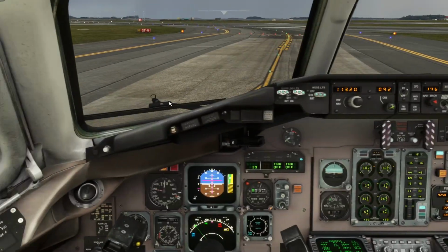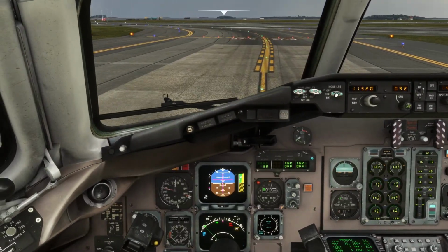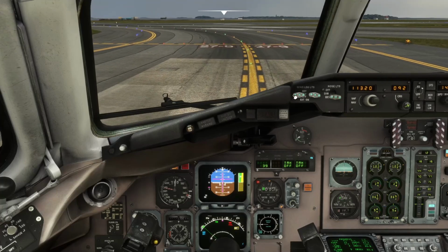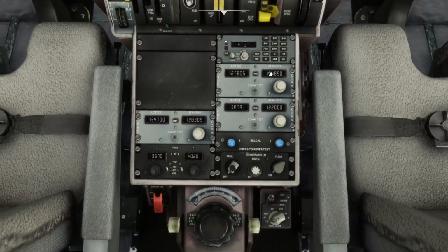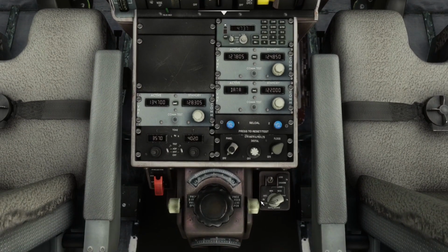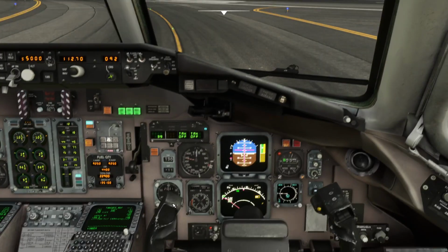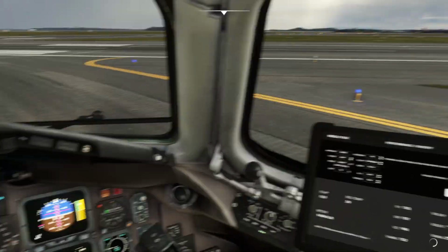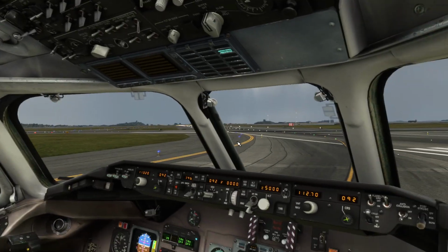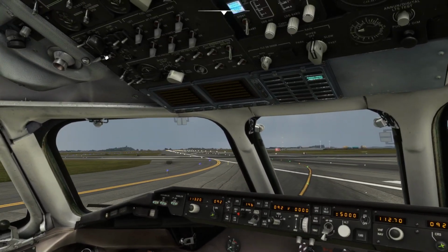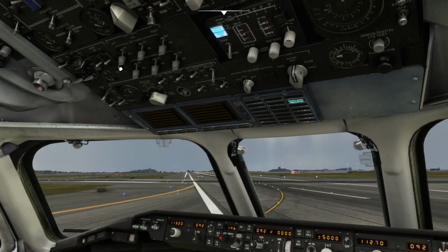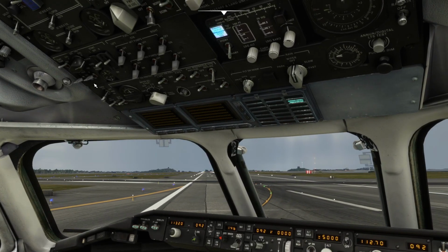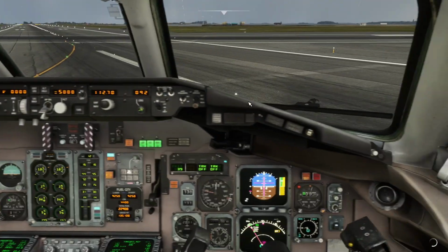Alright. JetBlue 1755, radar contact, say altitude. So nose lights on, we can extend and turn on the wing landing lights. Climb and maintain 14,000. Alright, we can turn these off, by the way, as well. Climb and maintain 14,000, JetBlue 1755. And check, that's clear, and that's good. So we can also turn on continuous ignition, which in this plane is just turning the ignition selector to both. And yeah, that's pretty much all there is to it.